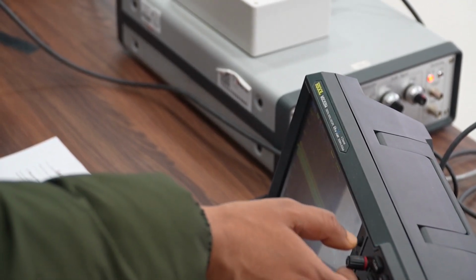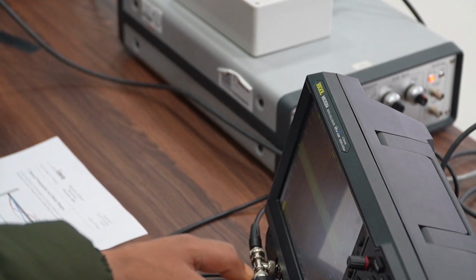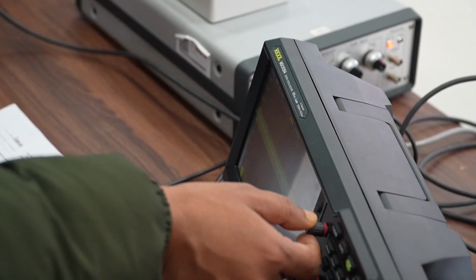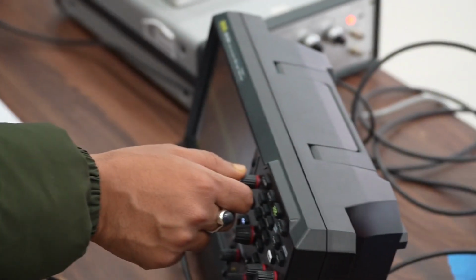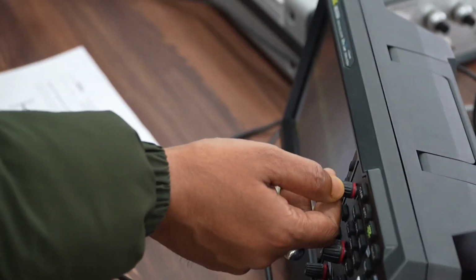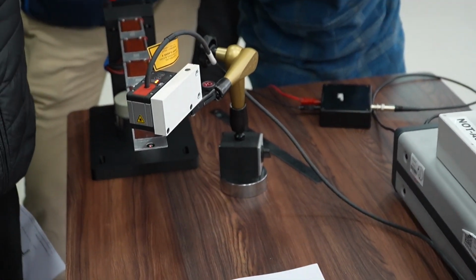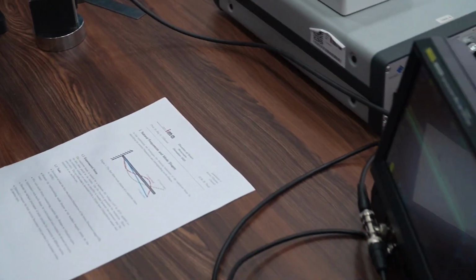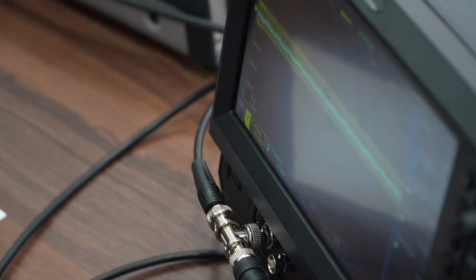Now let's see, I'll show you something. First of all, we need to get that a little bit down. More down, more down. Yeah, like that. Now we scale in to make both signals a bit higher, and we put it down until they overlay. Something like this. They're in different phase. Yes! But how much? Maybe not 180, but less than that. How much? Stop and check.